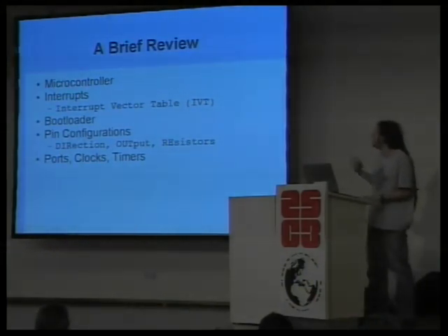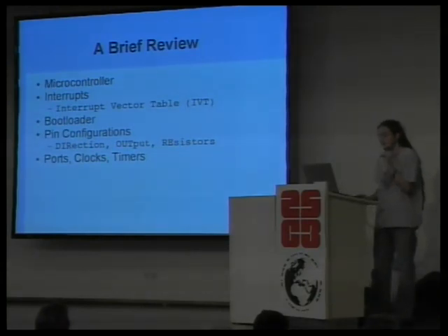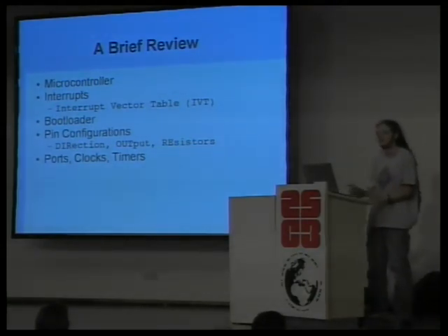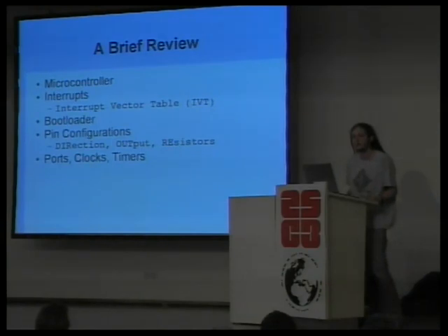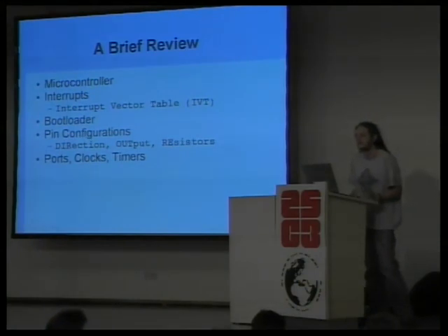I did a hack of the bootloader of this chip, allowing its password protection to be bypassed. And in this case, they actually wrote their own bootloader on top of that. So in addition to the bootloader that's in permanent mask ROM, there's also one in flash memory. So when I say bootloader in this lecture, I'm not referring to the same thing as I did in my day one lecture. And also, a microcontroller doesn't have a real operating system in it.